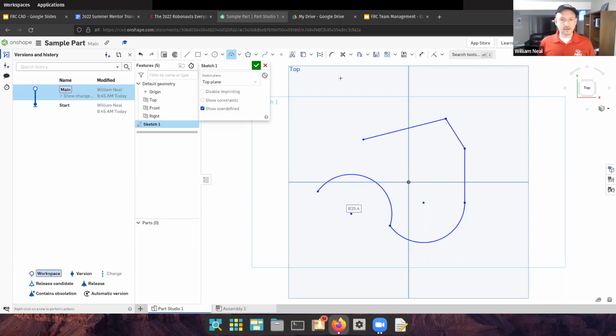And there I made a little arc, and we'll finish it off with some splines. Here's one here. Since I don't want any more lines, I'm going to escape. Oh, and I got it right the first time. It shaded it for me. That means it's a closed loop. So there's my shape. Don't know what it is at the moment because I'm just sort of showing the various features, how they can work together.